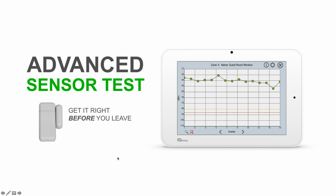This is going to check the signal strength for your individual sensors, and it's going to show you their dBm levels. If you're not familiar, dBm is a very granular, high-level look at signal strength for sensors. As you can see in this example, we log kind of a noise floor, right? So this red line on this graph is telling you that level of dBm where the panel can no longer hear your sensors. The yellow line is kind of the threshold. We want to make sure our sensors are talking above that line. And basically, the further above that yellow line the sensors are talking, the stronger they're communicating, right?